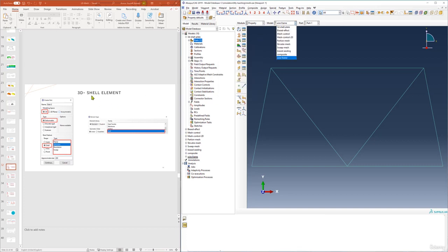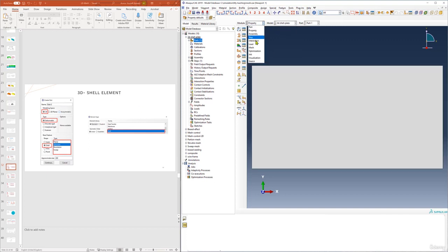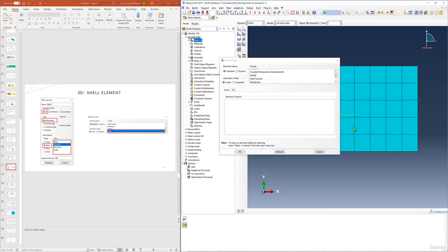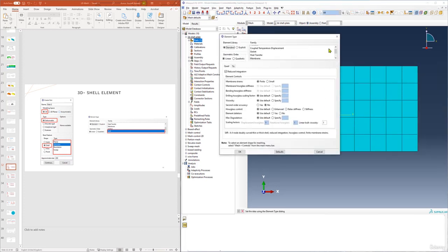The third one is the 3D shell element. So when you go to 3D shell plate, and go to mesh, assembly, and then select this one, you'll see that again I have some new items. We're not going to use the other ones because they're for more complex analysis.